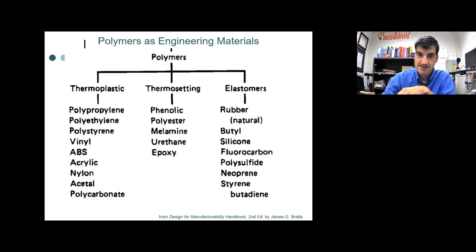With thermoset, it's kind of the opposite. If this was a thermoset, and I think it probably is, then you would not be able to remelt it down. It just wouldn't work. It would burn, but it wouldn't remelt into a liquid material that you could then reform into something else. The reason you can't remelt it is because those long polymer chains form covalent bonds between them and hold those chains together.